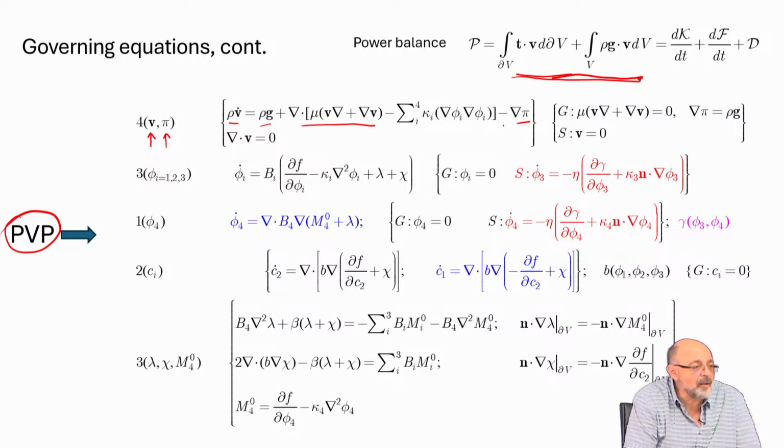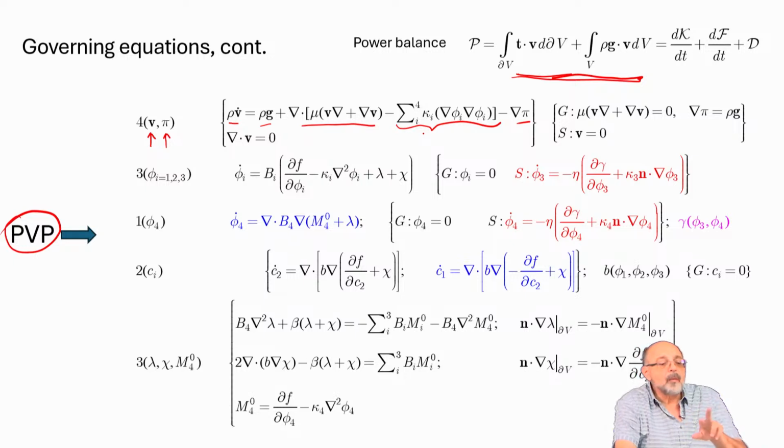This is all standard Navier-Stokes, well, fluid mechanics. These are capillary stresses. Notice that there is a contribution for all phases, but anywhere where this term exists, you will have mostly two phases, so two terms of this sum will be zero, except at those triple junctions, right, well, when they meet. But within pure phases, this term doesn't exist.